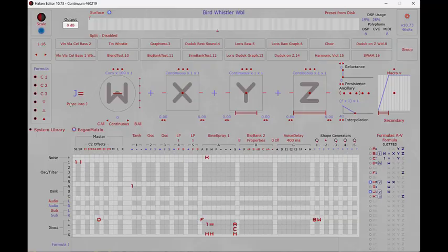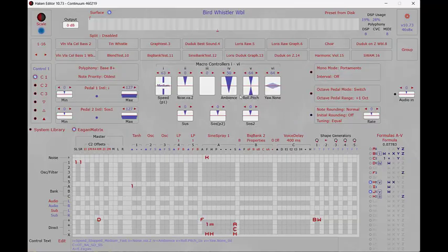So when I add them together, we get exactly what we just looked at, and you'll notice a little bit of hysteresis is applied here. So we'll go and trigger the roll, positive and negative, roll right and roll left. Notice there's a little bit of lag, a little bit of hysteresis after I start the roll. It doesn't start immediately, so if I'm not exactly centered, I won't be changing pitch when I don't want to.